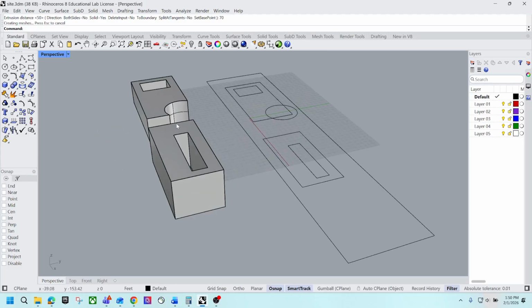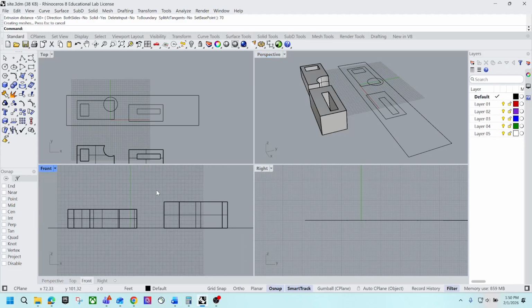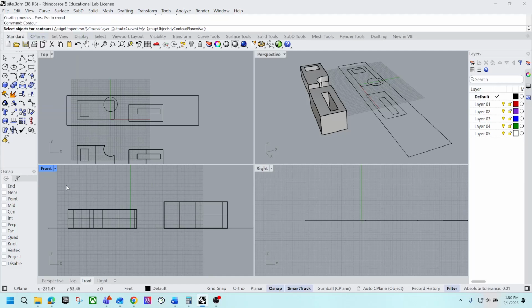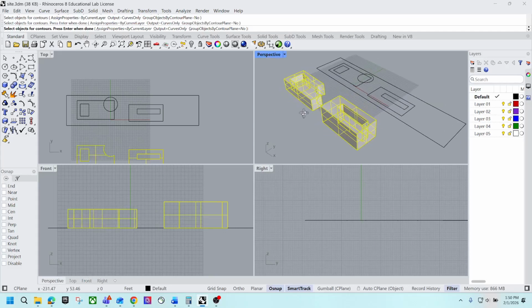And then for the total floor area, this is my way, I will usually do a contour to generate floor slabs. So I will do contour. This is a command you can use to cut horizontal lines out of a volume, right? So I do a contour, and I can pick up both volumes, so these are the two massing models I picked up.